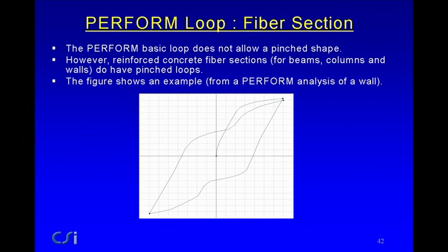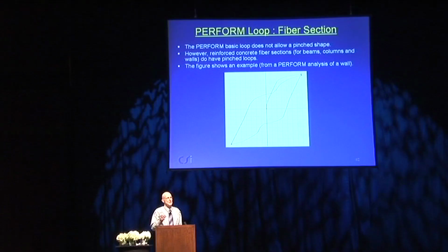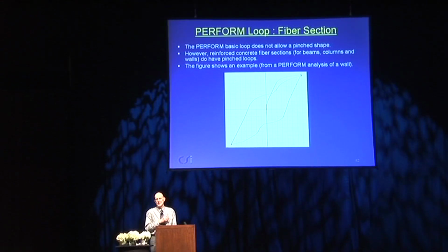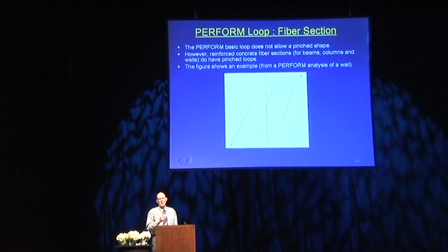There is no provision for pinched shapes directly. However, this is a plot of a hysteresis loop obtained by doing a cyclic pushover on a wall with a fiber cross-section. The fiber cross-section automatically will give you a pinched hysteresis loop. So this comes out of the analysis. It's not something which is specified directly.